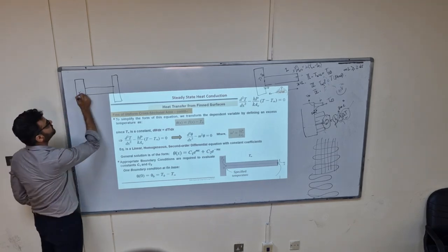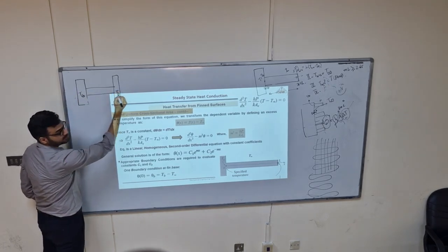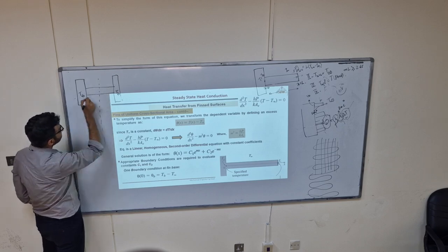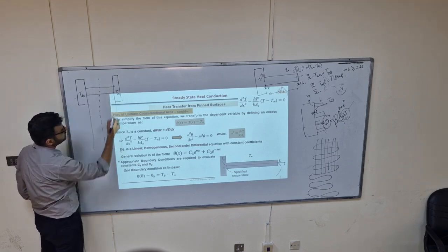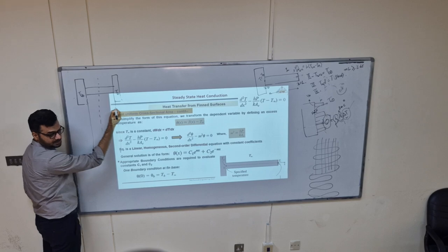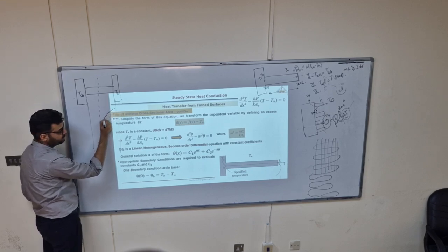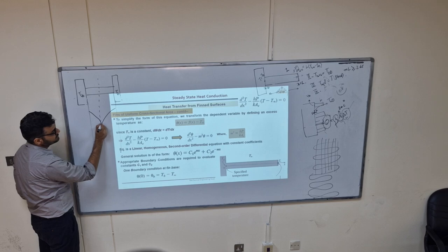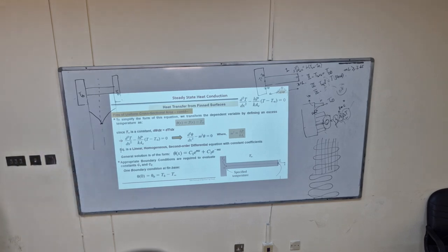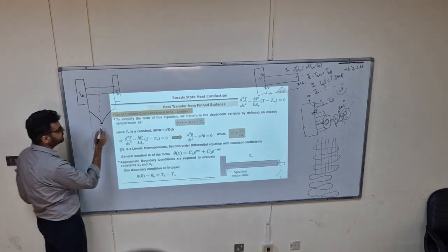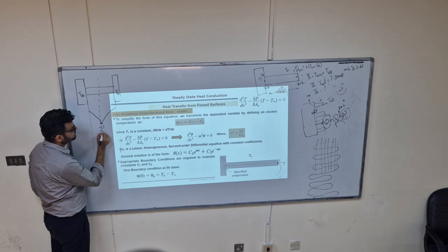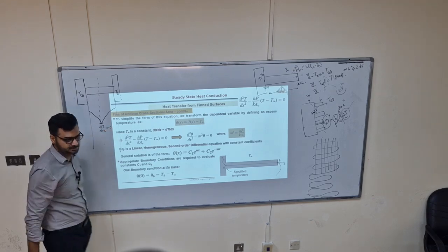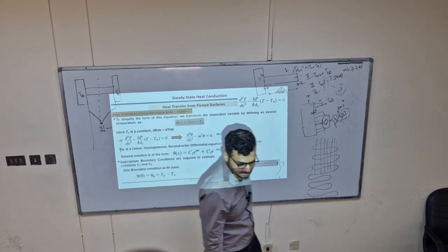Okay, so here you have TB, here is that fin. So at the center, from here to here, how will the temperature be dropping? Temperature will be dropping within the fin like this, symmetric. So at the center, dT/dx is equal to 0. This is what condition? Insulated.